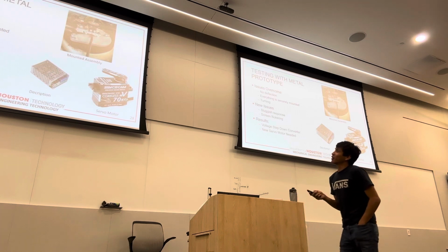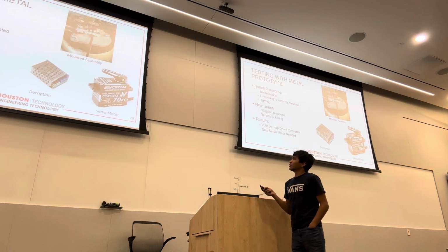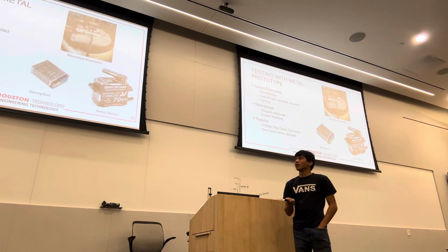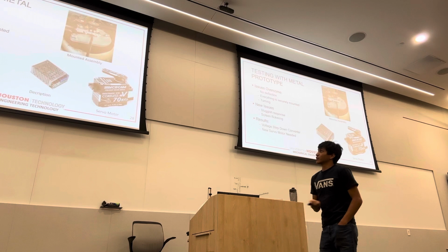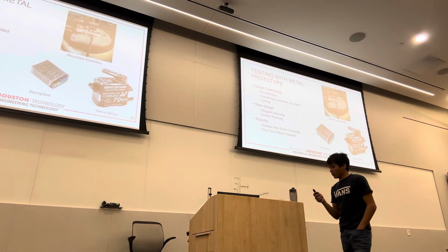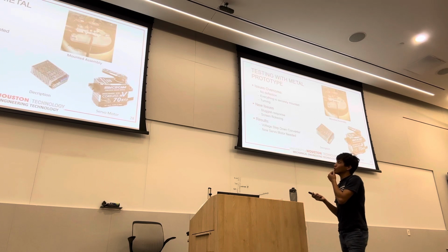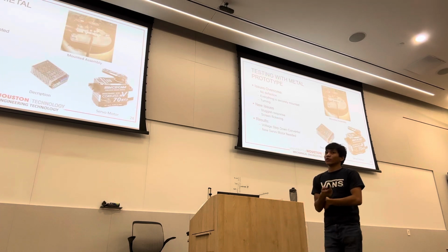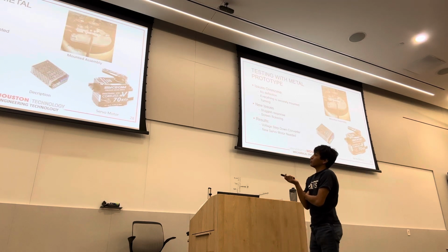Okay, so from there we were able to troubleshoot what was going on, and we realized that one, we were underpowering the motor this whole time. Two, the screen flashing is obviously really bad for the system, so we needed some type of separate voltage source for just the servo motor. That's where we were able to get this voltage step down converter. The car is 12 volts, and we're able to step it down to the 7 or 8 volts a servo motor would normally require. So that was a simple fix.